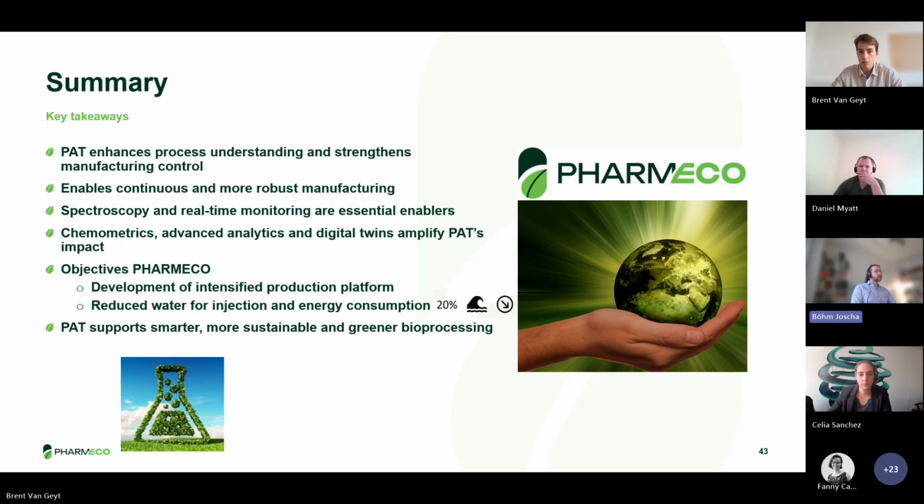I think there's a big risk in terms of AI if you want to use the total process model as AI, since then you don't have any guarantee that you stay within the physical bounds, where usually some mechanistic structure in the top layer of the model ensures that you stay within physical bounds. Using AI to focus on the parameters that are hard to gather otherwise is certainly helpful in terms of process modeling.